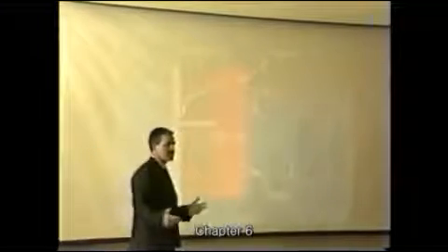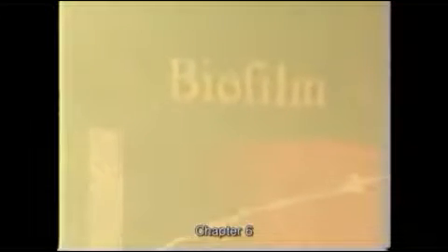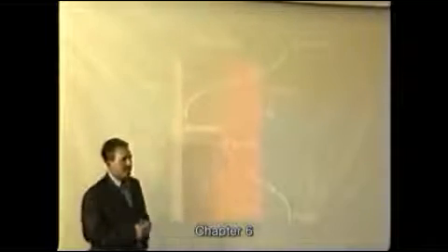Biofilm processes work on the same principle. The biofilm processes have this advantage that you automatically have an anaerobic section in your biofilm, because oxygen only penetrates about 150, maximum 300 micron. So if your film thickness is 500 micron, maybe 1 millimeter, the rest is all anaerobic. So your substrate goes all the way in, but not your oxygen. And in the biofilm system, the main problem is always oxygen.